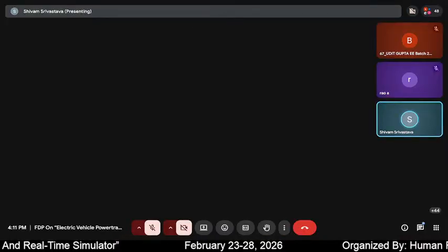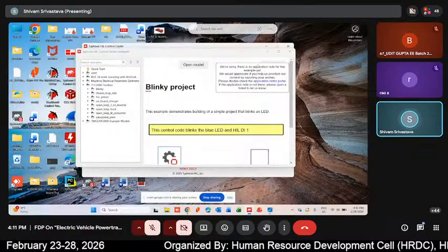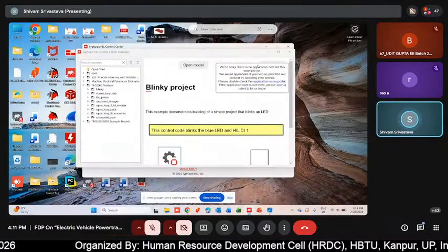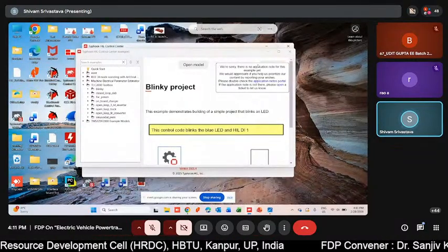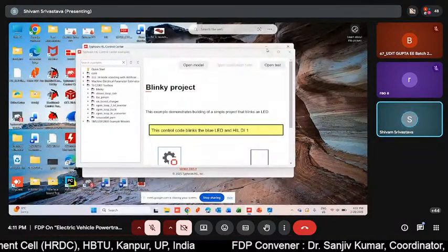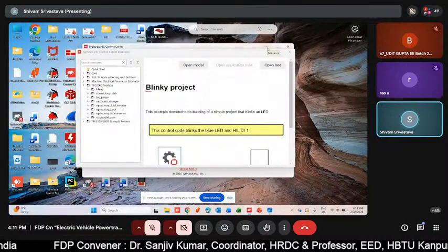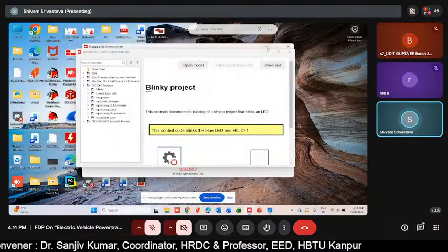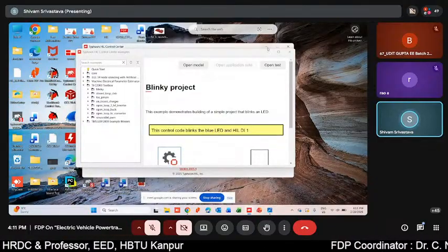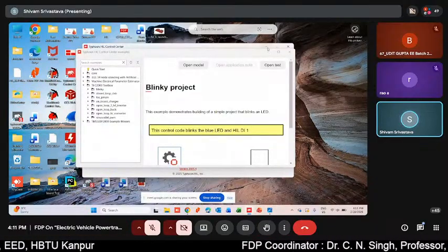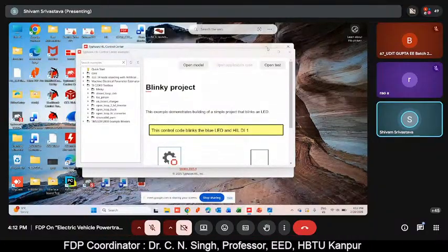So this is giving you the leverage of auto code generation. One thing you must do after installing the package: you need to install two software in your system, the C2000 Warehouse software and the Code Composer Studio software. You need to install these two, but you need not open them at any cost, because we are going to flash or generate the code from Typhoon itself.